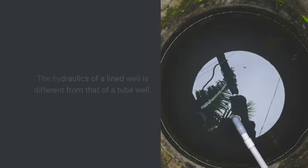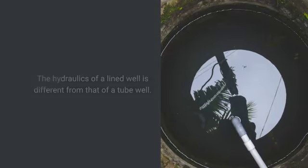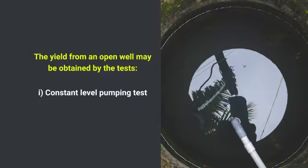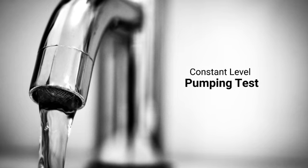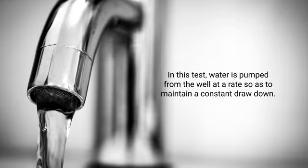The hydraulics of an open well is different from that of a tube well. The yield from an open well may be obtained by the constant level pumping test and the recuperation test. Constant level pumping test. In this test, water is pumped from the well at a rate so as to maintain a constant drawdown.